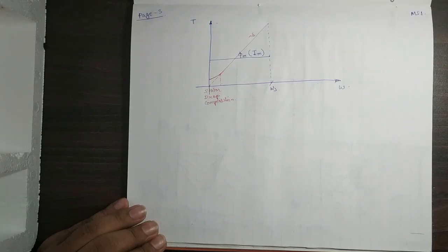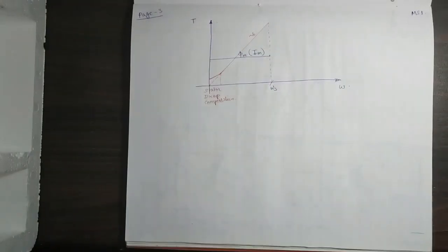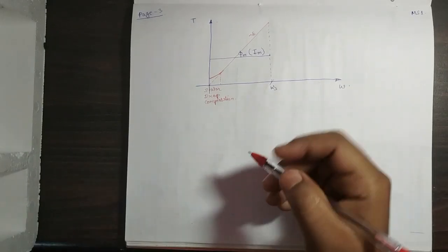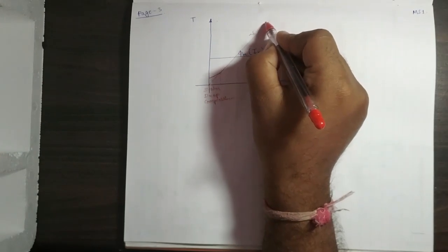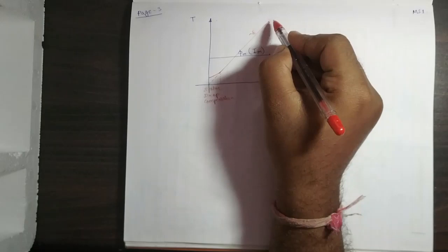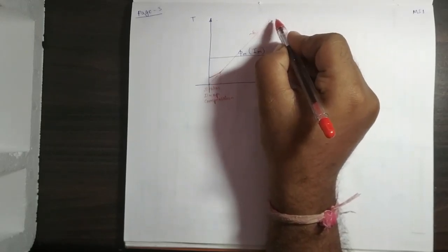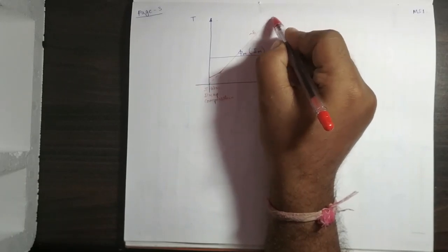After some part, the winding in the machine can sustain a certain amount of voltage above which it cannot sustain. So the stator voltage has a definite value till which it can reach. After that, if you increase this voltage, the windings of the machine will be burnt out. So after this value, it cannot move.